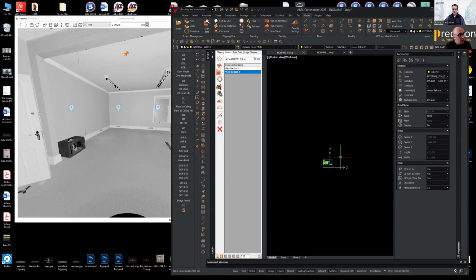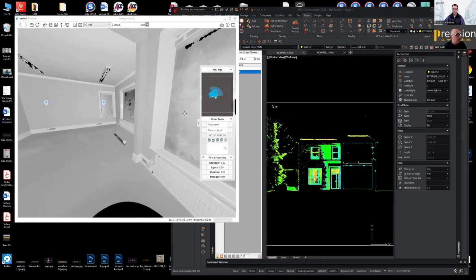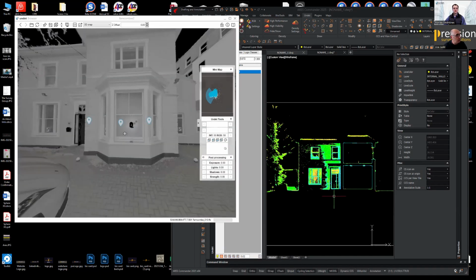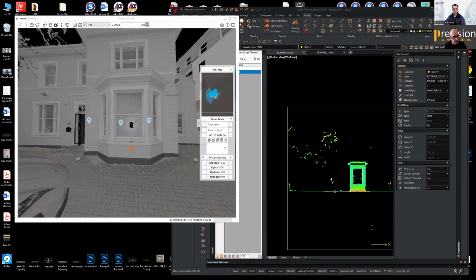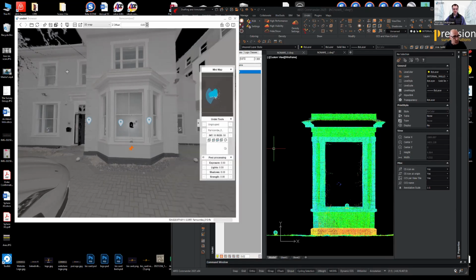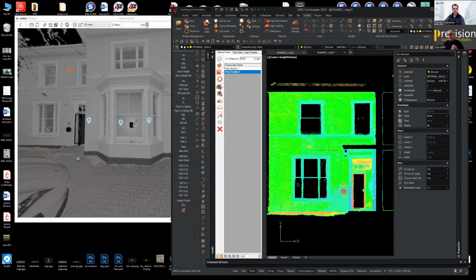Right, so we're looking at our building, like we were, as though it was a plan, but let's now go outside the building and utilize our translate view sections. Let's say, for example, we want to draw the front of the bay window. Again, we can navigate our point cloud so that we only get to see the parts of the building that we want to do. We're going back to that wall line, and we can digitize by using the translate view section, and we can move ourselves in and out of these elevations without having to grab and pull grips.